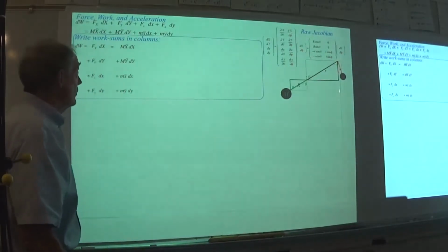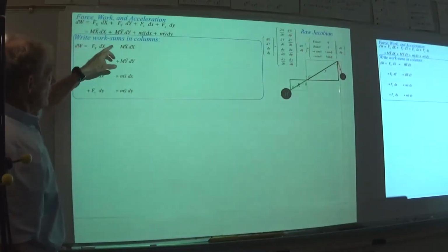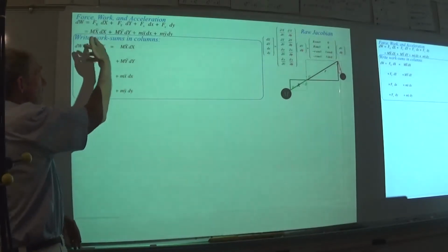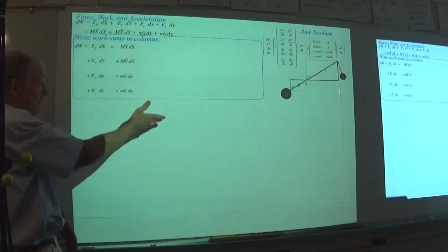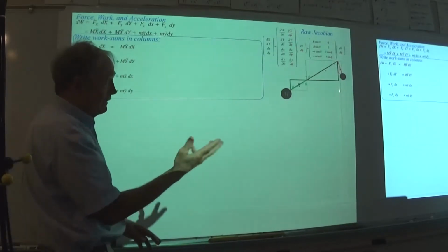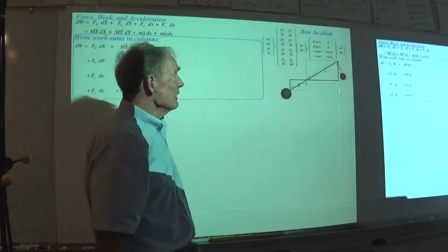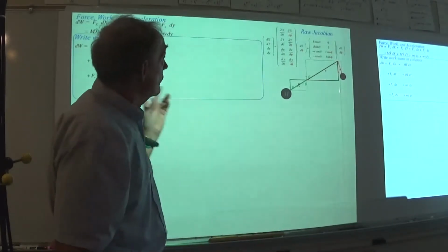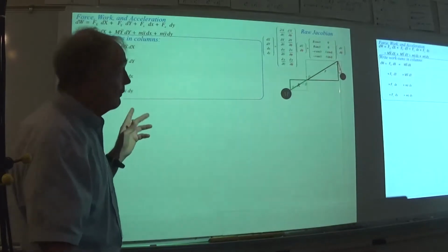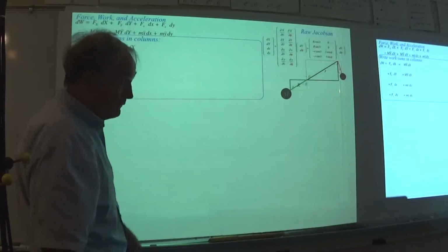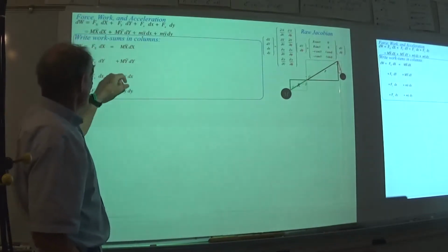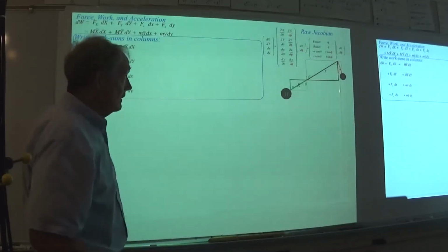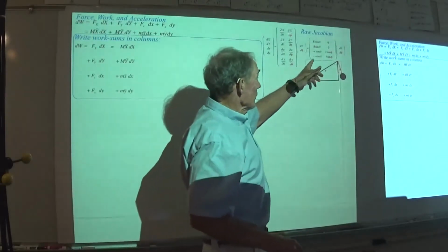So here's where the arithmetic associated with building the work differential that you start with to get Lagrange's equation is different than what we did with simple polar coordinates. There it was 2 to 2; here it's 2 to 4. So we have to be a little careful with having 4 here and only 2 for our theta and phi, which we're about to use the Jacobian to produce.